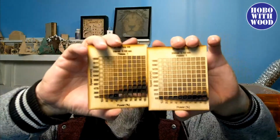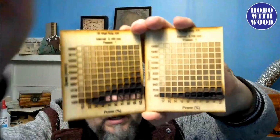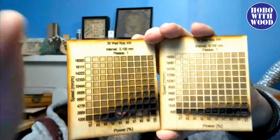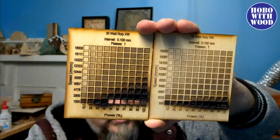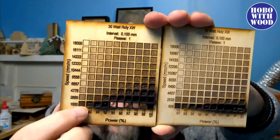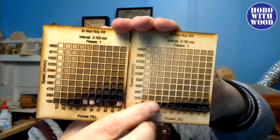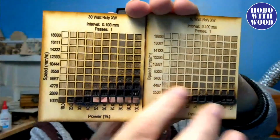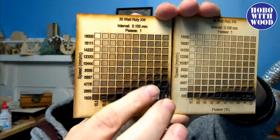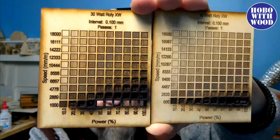I've got these two side by side. Whenever I got this material in, one of them is at 10 watt. This one's at 10 watt. This is at 30 watt. And you see the difference. The speeds and powers were the same from 1,000 to 18,000, and this one was from 600 to 18,000. But see, the 30 watt just had a lot more burning away of the material, and I wasn't getting a really good, clean, dark, crisp burn.